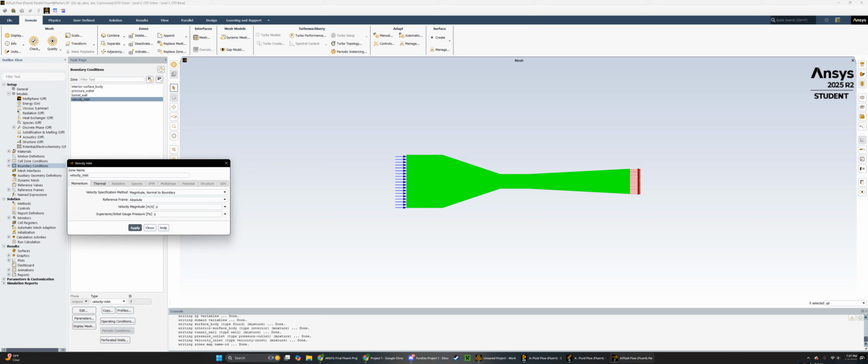Ozbay wanted the test section to have 15 meters per second, so I did A1 V1 equals A2 V2. I got the velocity that it should be in the beginning, and I got 4, and then I tried it out, and it was pretty close. It was very close to 15.